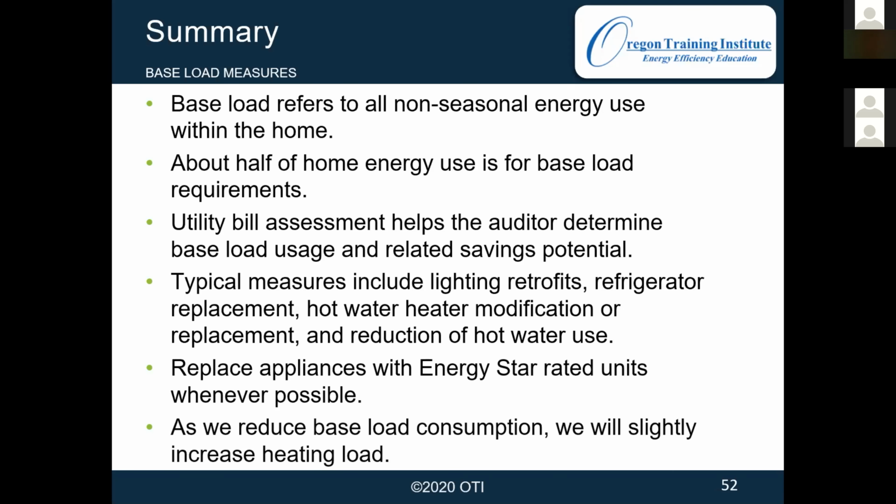And another thing to be aware of, especially when we're doing our modeling software, is that as we reduce base load, the byproduct of base load where the energy is being wasted, that's mainly going to heat. So as we reduce base load, the heat load of our home is going to increase.